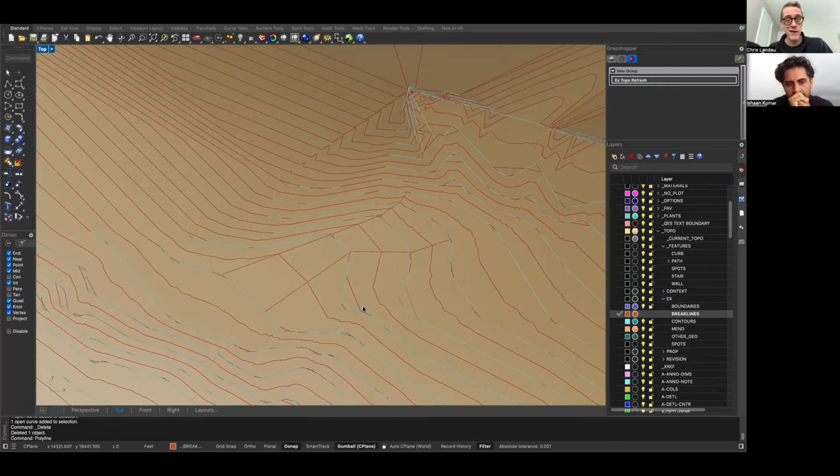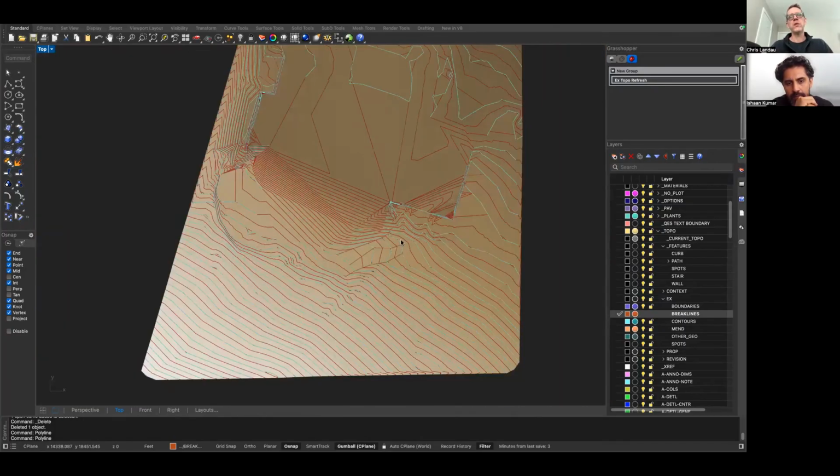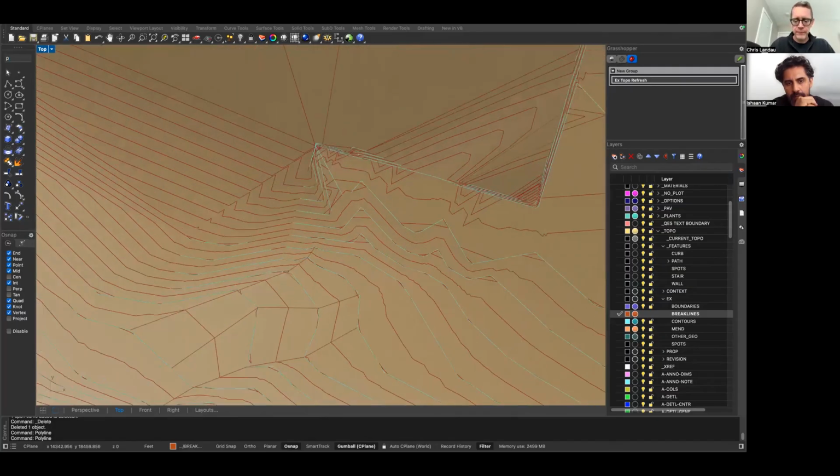This is really important if we're doing water analysis, because water is not going to flow down a swale if it's not actually represented, giving that information, that level of detail. Aside from it not looking good in a rendering, I think it's really important to actually represent this. And this is something that a computer doesn't know. When it looks at contours, it just does not know how to draw those contours. So it's important. We always look for the places where these ridges and valleys occur. That's kind of how we talk about them, ridges and valleys.